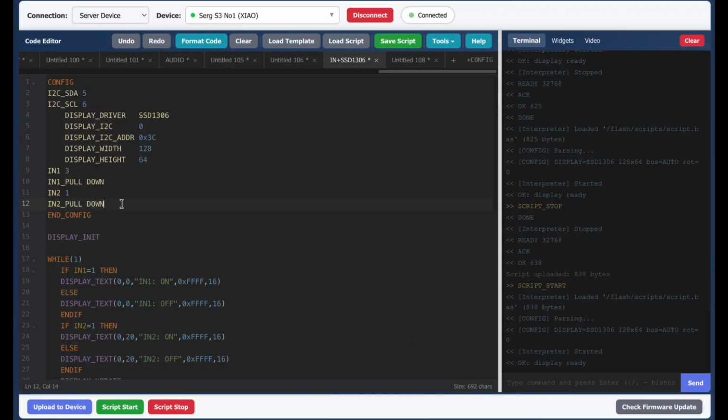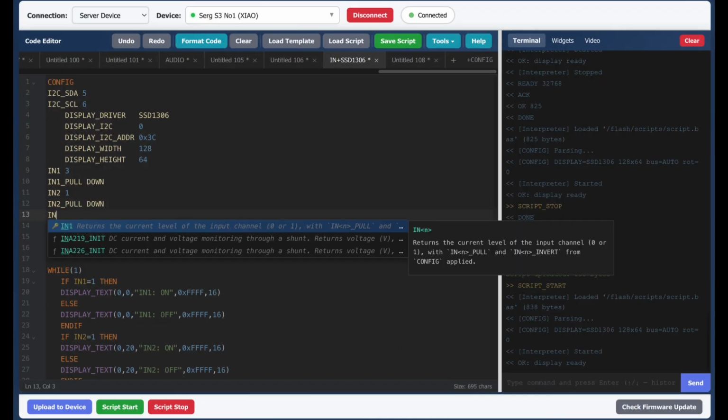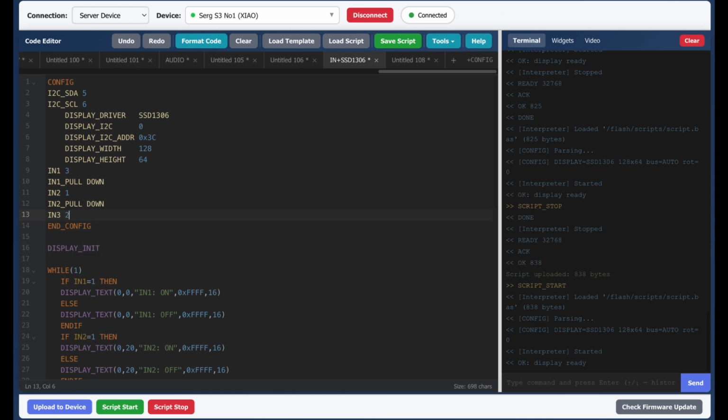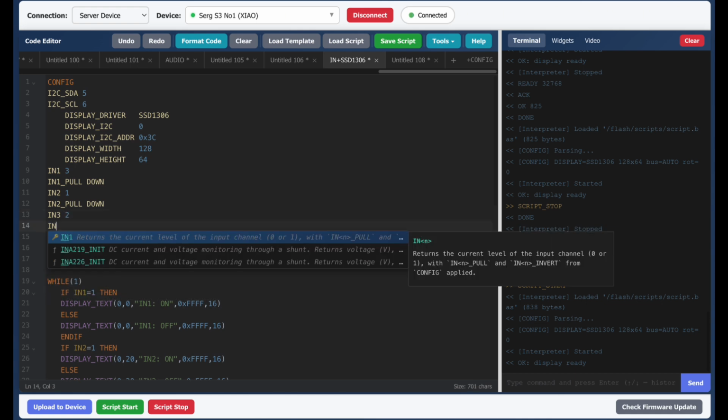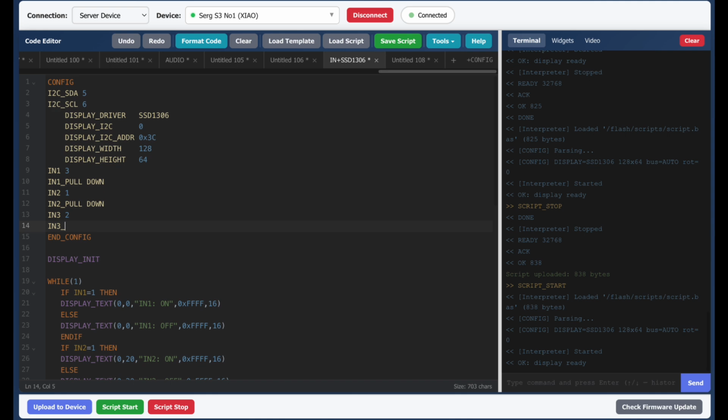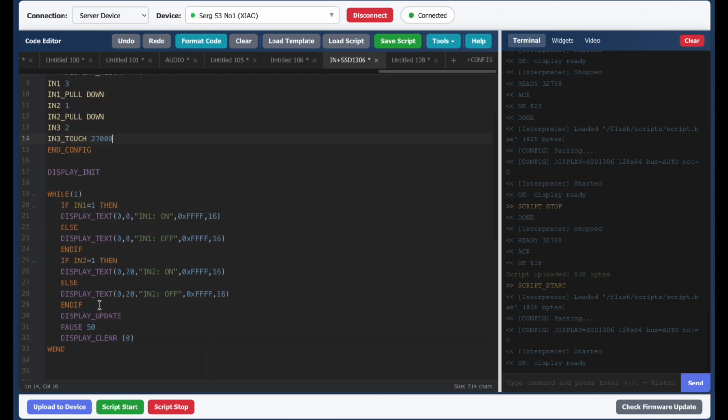Touch, capacitive touch input. Now let's look at another interesting digital input mode, the capacitive sensor. It's supported on ESP32 S3 and P4 boards, and, unlike a regular button, it requires no mechanical contact at all. The principle is straightforward. The touch pin is connected to a metal electrode, a piece of foil, a copper wire, or a pad on the board.